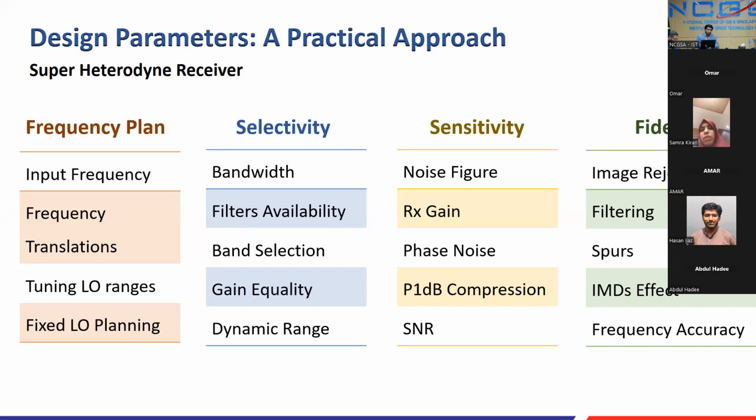Then you have intermodulation, IMD effects. Intermodulation in communication systems has a formula of mF1 plus minus nF2. When you feed two frequencies to a mixer, one from the LO and the other from the RF source, you have plus minus, a lot of mixing products. When the mixer is overdriven, those mixing products themselves mix and they form IMDs.